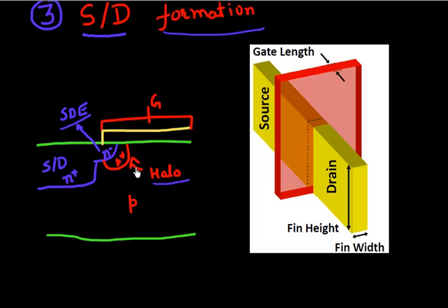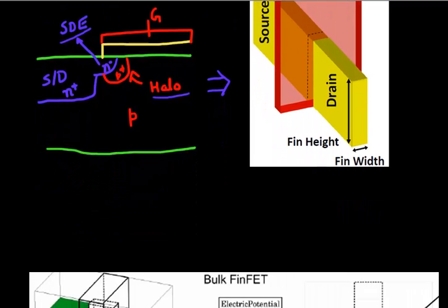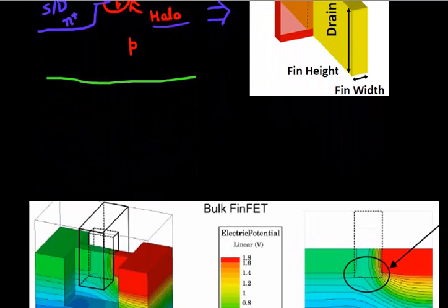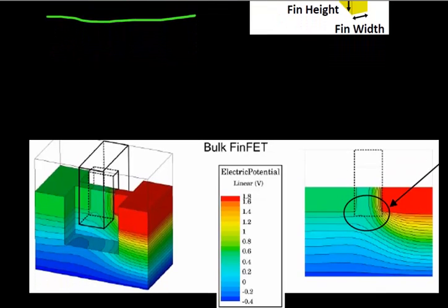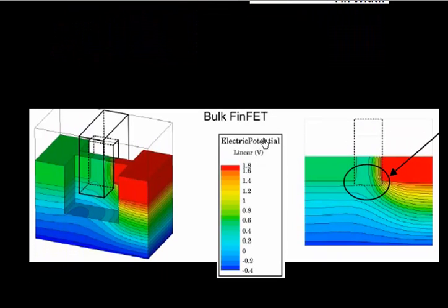So how does that change in the context of this FinFET device? As we go from this planar to this 3D structure, how does that change? One of the advantages of going to this FinFET device that I've laboured upon multiple times is that you get a much better gate control.